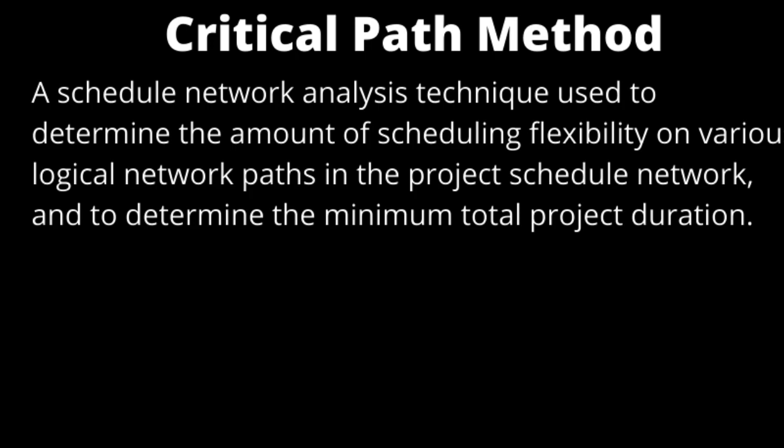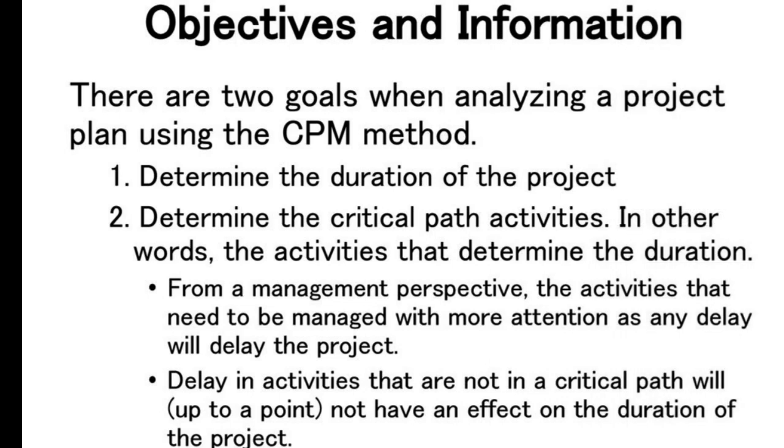The critical path method (CPM) is the most commonly used technique for scheduling in construction. It is sometimes referred to as critical path scheduling because it mainly calculates the minimum time needed to complete a construction project, alongside the possible start and end times for the different activities.